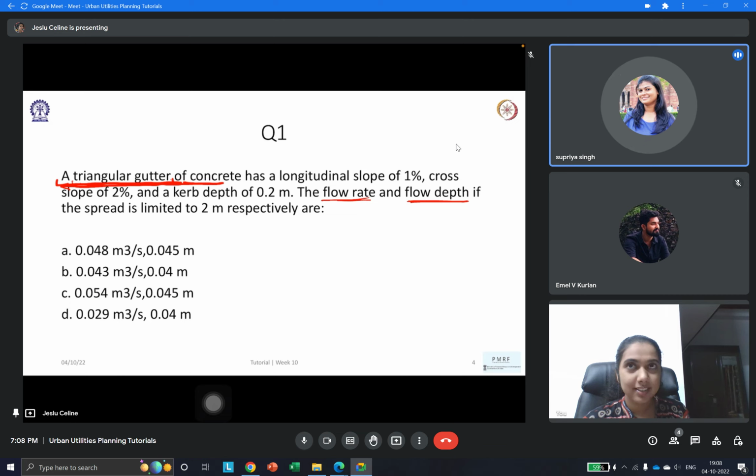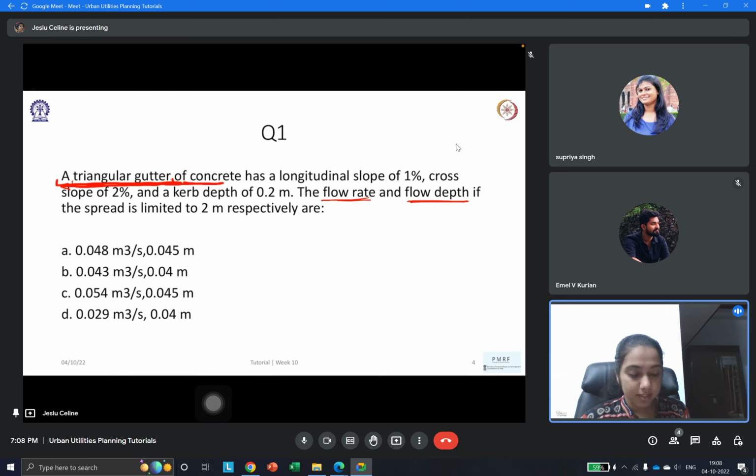We get maximum vertical length. Okay. So basically, we want water to slope down and fall into the gutter, and through the drain, we want water to come to the stormwater drainage channel which we have designed. In roads or pavements, we would have a curbstone, and then there'll be a gutter which is sloped, and sometimes there'll be an opening here so that water slopes down and falls into the drain this way.